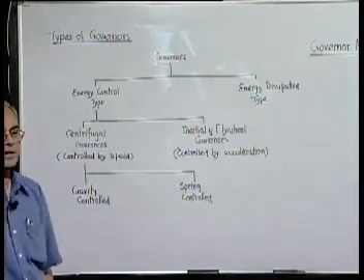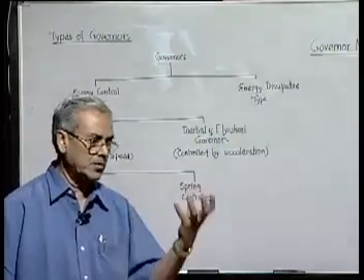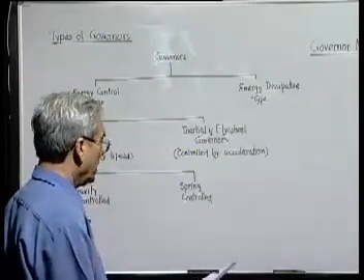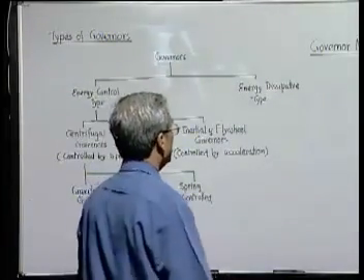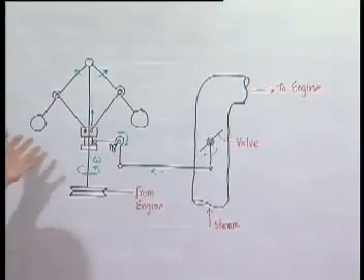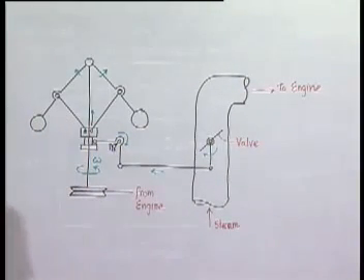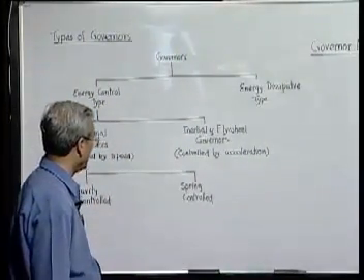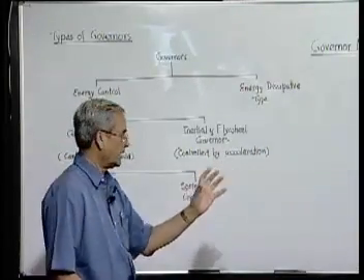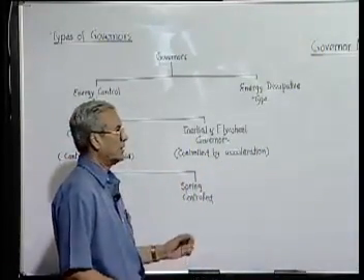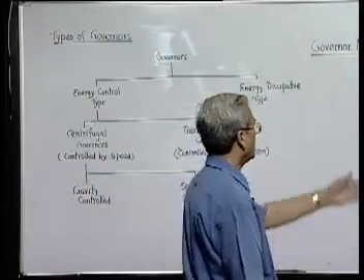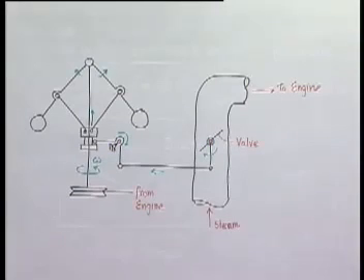Obviously, you can see that gravity control means generating enough force to operate the whole mechanism with the help of gravity. The mass of these rotating spheres will have to be quite substantial, and they are quite heavy and bulky. On the other hand, you can generate a substantial force of restoration using even small or very stiff but small springs. So such devices are definitely very compact compared to the typical gravity controlled governors.